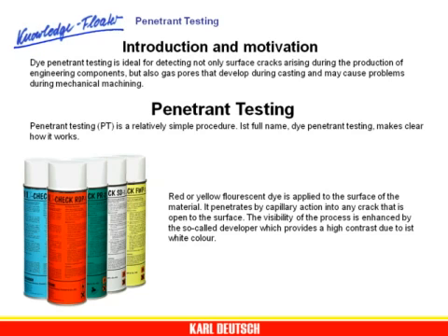Red or yellow fluorescent dye is applied to the surface of the material. It penetrates by capillary action into any crack that is open to the surface. The visibility of the process is enhanced by the so-called developer, which provides a high contrast due to its white color.